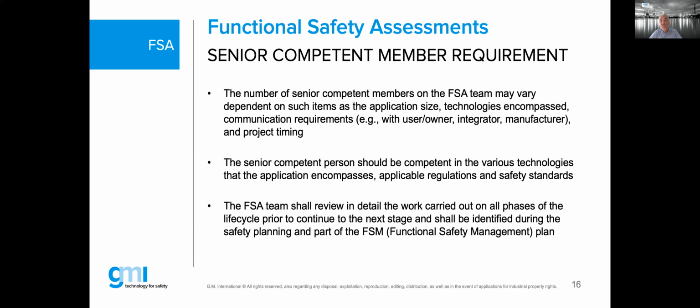So the number of senior competent members of an FSA team may of course vary on such items like what is the size of the application they have to make a judgment from, or the project they have to make a judgment from. Also what type of technologies they are looking at. I've been part of some assessment teams, and I was only there myself personally for the safety PLC bit inside their SIS. We had some specialists on valves, we had some specialists on the reactors with us.